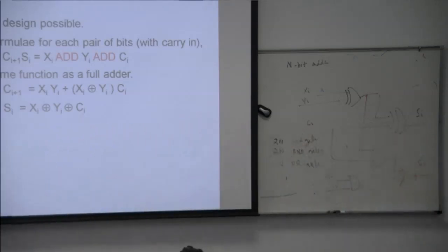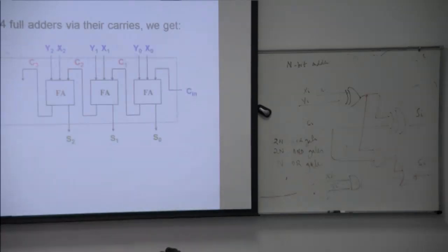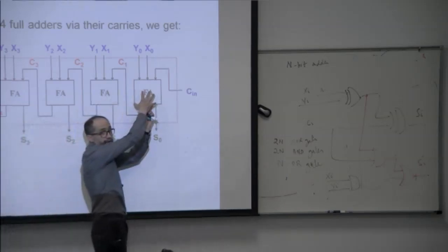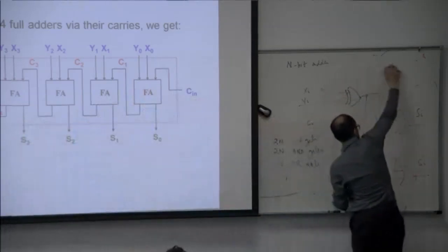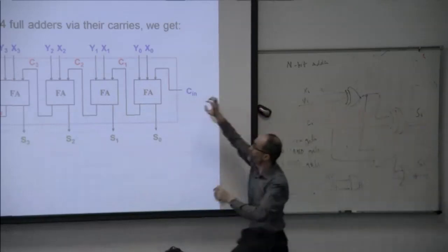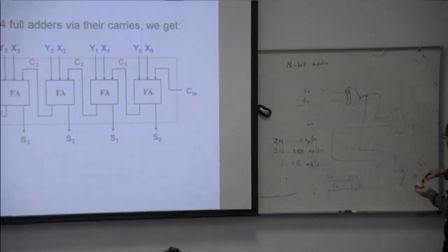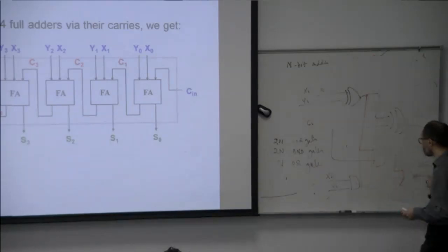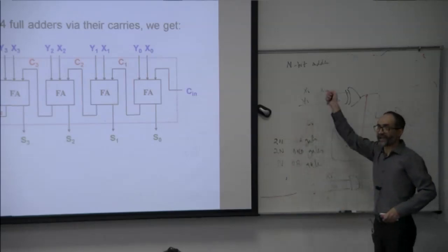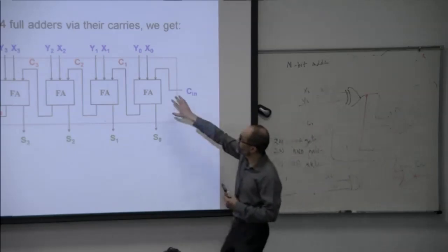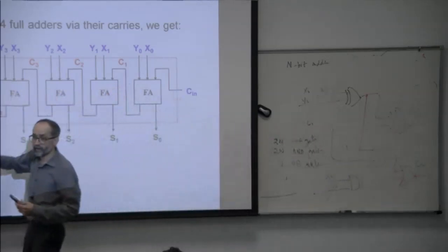Okay, so now this is how it works. Now it is a cascading 4-bit adder. This is a full adder block diagram with its complete inputs. We copy this and paste it, and this output is Ci, not Si. This output Ci becomes the Ci for the next stage, which is i plus 1. So now we have these gates here, and gates here, and this is how it works.